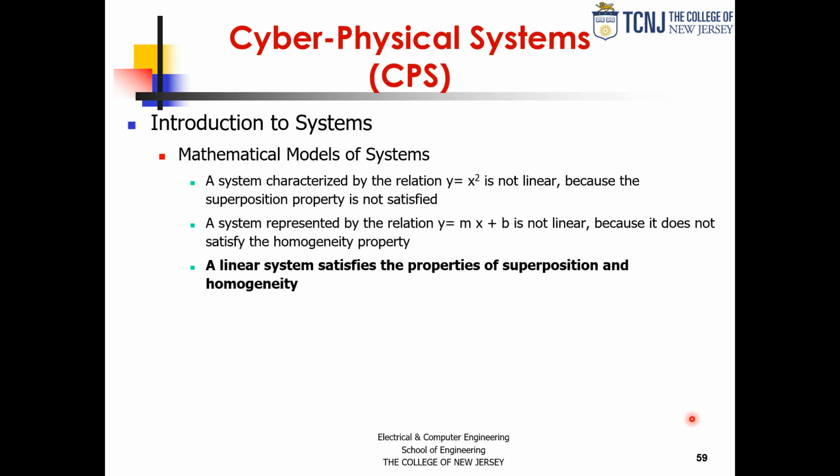So like if you are measuring something like a conductivity, when you apply the equation, if you have an offset in the voltage, since the conductivity is current over voltage, that voltage offset that we work so much with, I mean, everything is some type of voltage signal, that voltage offset in the denominator really makes your system nonlinear and very difficult to nullify, and introduces a lot of error in your system.